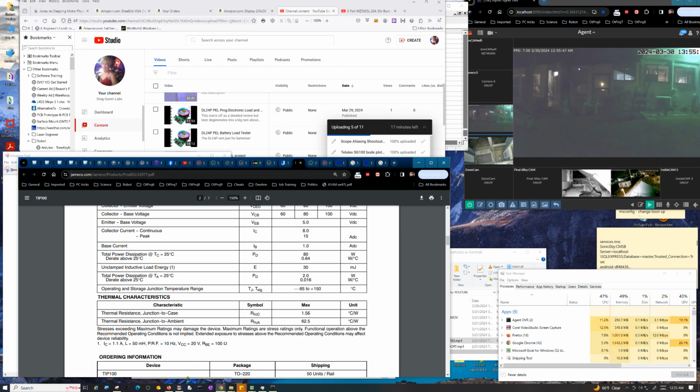I just have a tendency to go off topic. I hate doing that. But yeah, if your transistor were dissipating 10 watts, well, that'd be 15.6 degrees, okay? But that's the temperature of the case. It's not the temperature of the ambient air. So that's about the only time you really use this figure, at least for me. That's the only time I've ever used that figure.